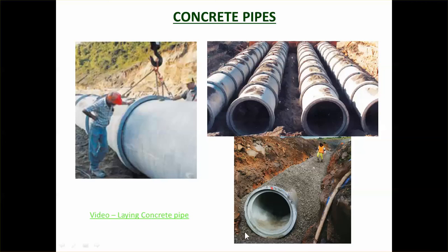You can see that it's got a bedding right around it. Not so important with concrete pipe, but you still make sure that you do it. You need that lateral support there. It just increases the resistance to external loads. If you get an external load on top of this, it does tend to crack it either on the top or on the sides as it tries to form the shape of an egg. So you do need that lateral support and the proper bedding to support it.